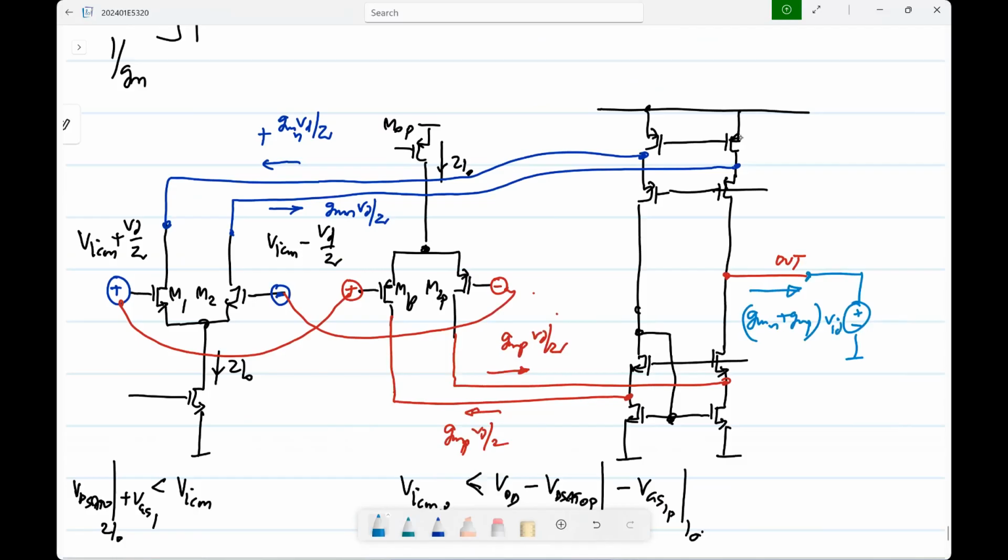Okay. So you get the sum of these two, right? But what happens now is that the NMOS differential pair, for very low input common mode voltages, just turns off because this voltage becomes too small, and then that's it. The currents become very small, and that's the end of it. But the PMOS is still active. Similarly, for very high input common mode voltages, the PMOS turns off and the NMOS is still active. Overall, the op-amp is active throughout the range.